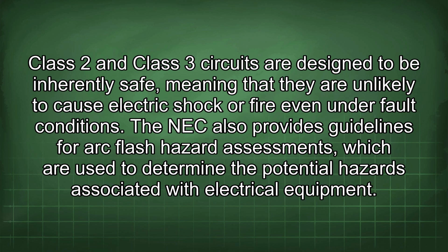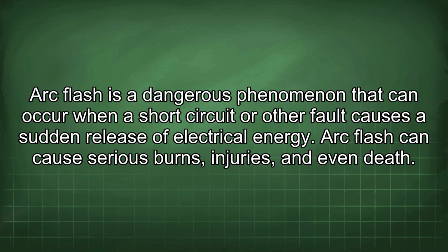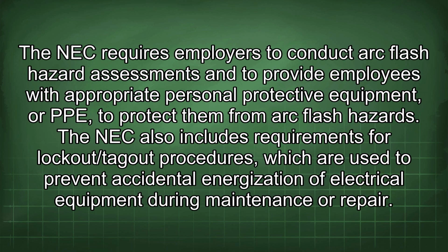The NEC also provides guidelines for arc flash hazard assessments, which are used to determine the potential hazards associated with electrical equipment. Arc flash is a dangerous phenomenon that can occur when a short circuit or other fault causes a sudden release of electrical energy. Arc flash can cause serious burns, injuries, and even death. The NEC requires employers to conduct arc flash hazard assessments and to provide employees with appropriate personal protective equipment, or PPE, to protect them from arc flash hazards.